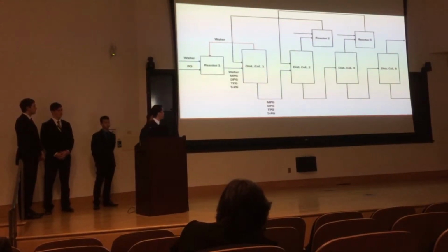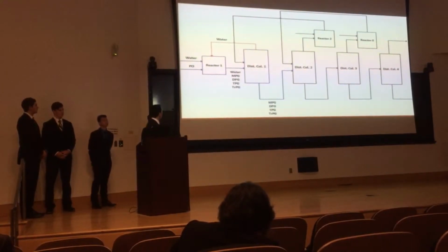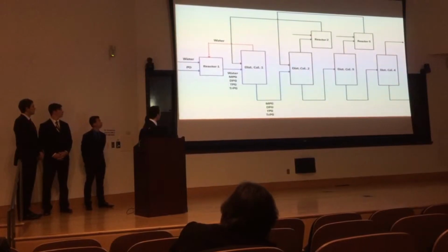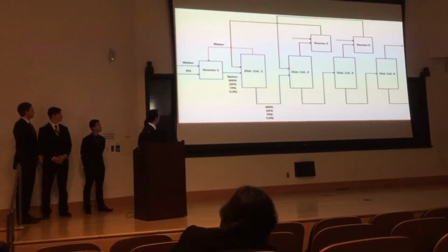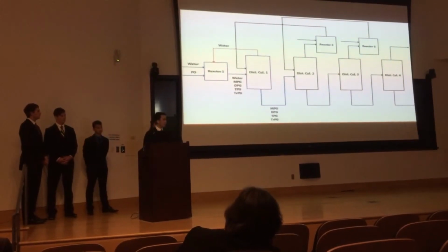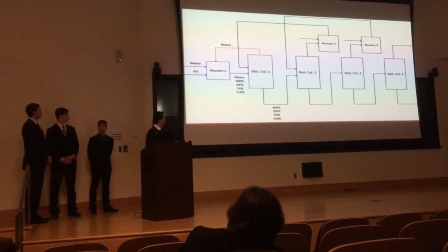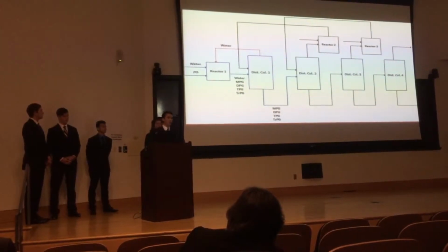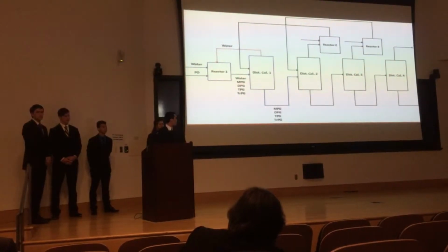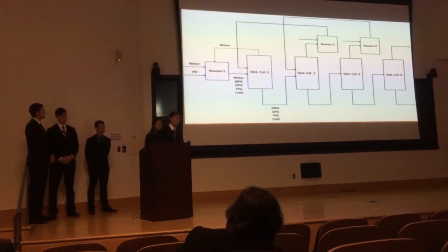I'm going to walk you through each stage of the process. First, we have propylene oxide react with water in the first reactor. Based on the reaction chemistry, the main product comes out, monopropylene glycol, but we also have other glycol products, including dipropylene glycol and tetrapropylene glycol.